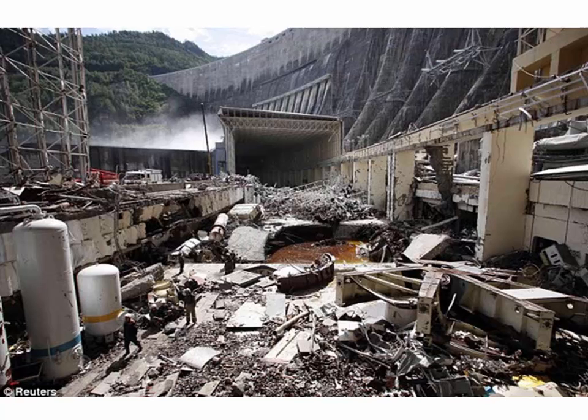That's the process of cavitation, and it sends small shock waves through the pipe. Any one little water vapor bubble that collapses isn't going to cause this. But over the long term, the structural integrity of a pipe can be eroded as the tiny little water vapor collapses chip away at a pipe.